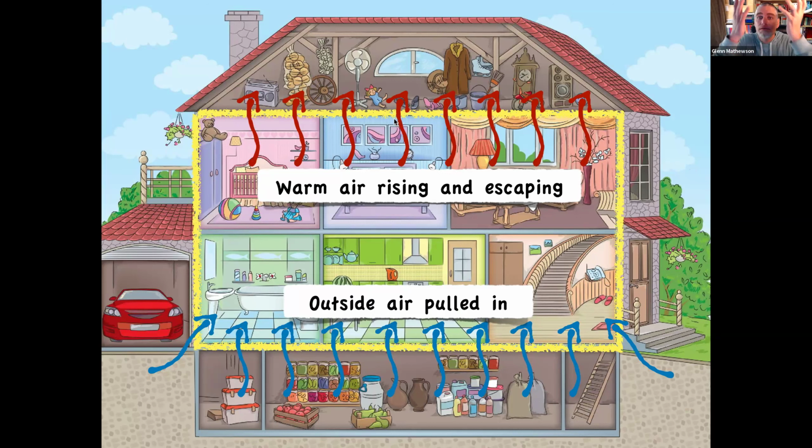If the air is leaving, it's going to be drawing more air in, whether we have no wind. So this is why we often see the first advice for air sealing on older homes is to get up there and air seal your attic. Stop the air moving out so it stops the negative pressure wanting to draw air in from below. But then, of course, sealing other locations is great for issues like wind pressure. That's a different pressure that may be moving our air in and out.